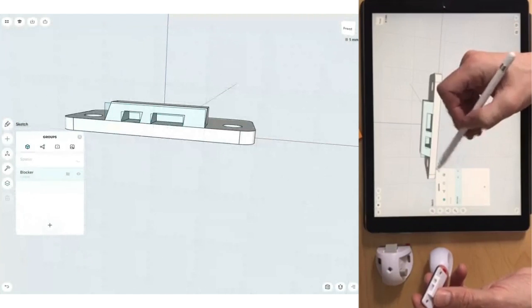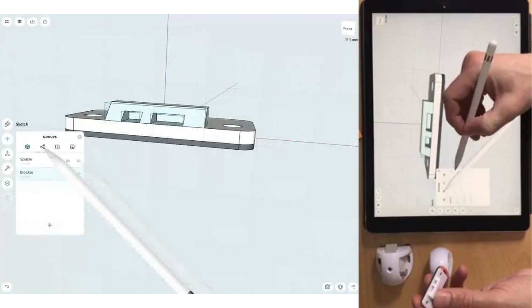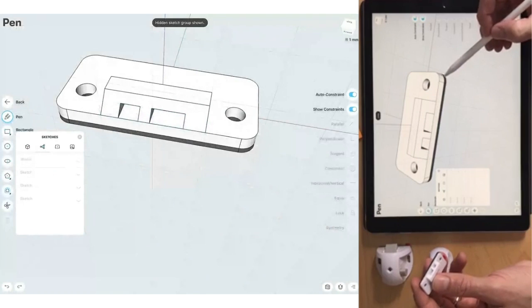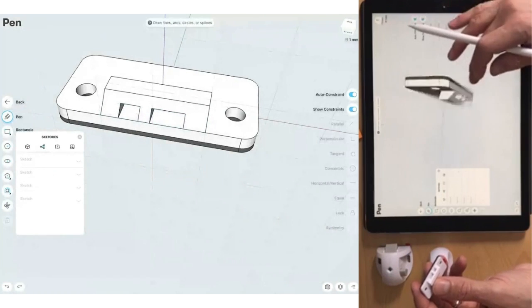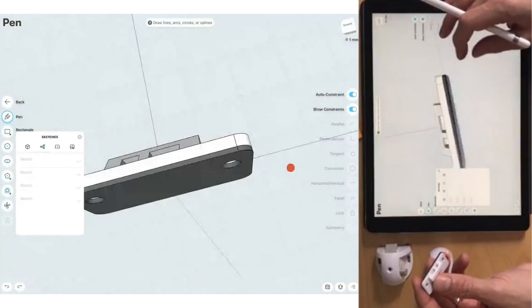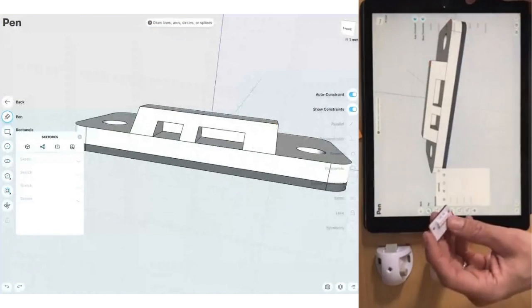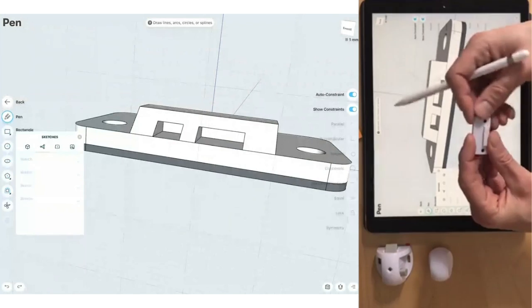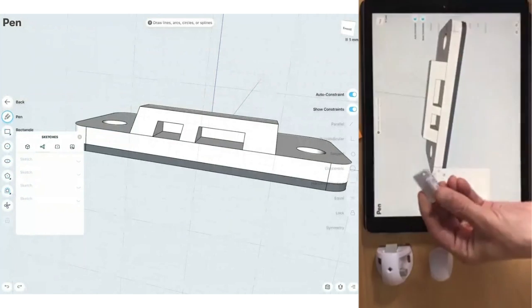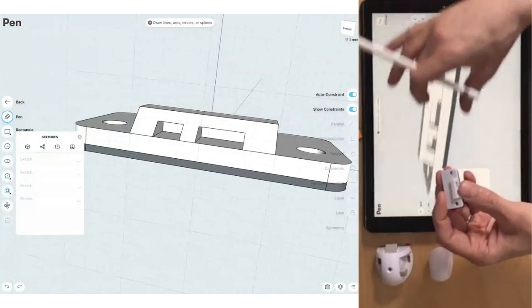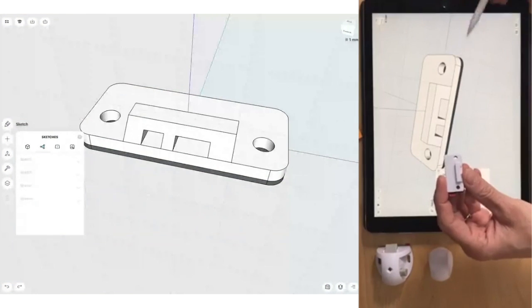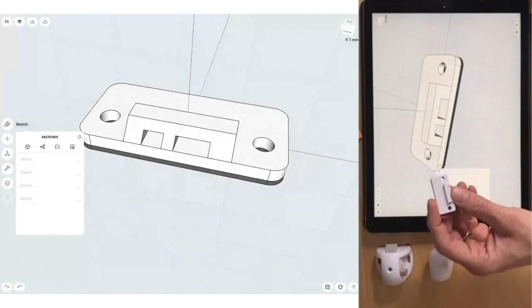See, not very complicated. Fillets, besides on the big edges here, but along the smaller edges, I do most times only when really the design is done, because these are like surface treatments. So when this is manufactured, you don't have sharp edges. They're not really defining the design, unlike, for example, this edge. So at this point now we could go ahead and add fillets, etc.